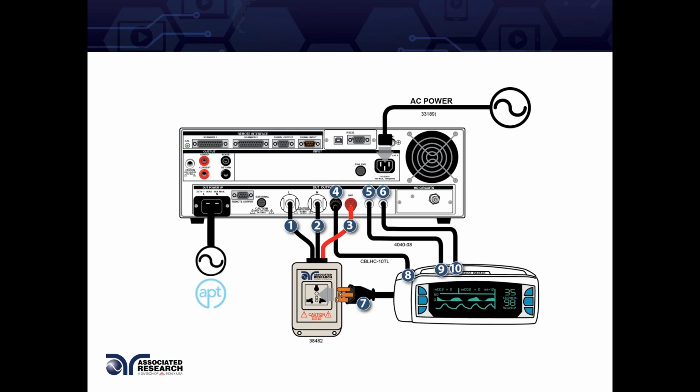This is the AC source that's feeding power to the device under test to power on. If you look at different leakage current testers, some come with a built-in AC power source, some don't. In this case, we're showing one without an internal AC source, and that's why we're required to use an external AC source. And again, it has to be an adjustable AC source so that you can set the correct voltage.